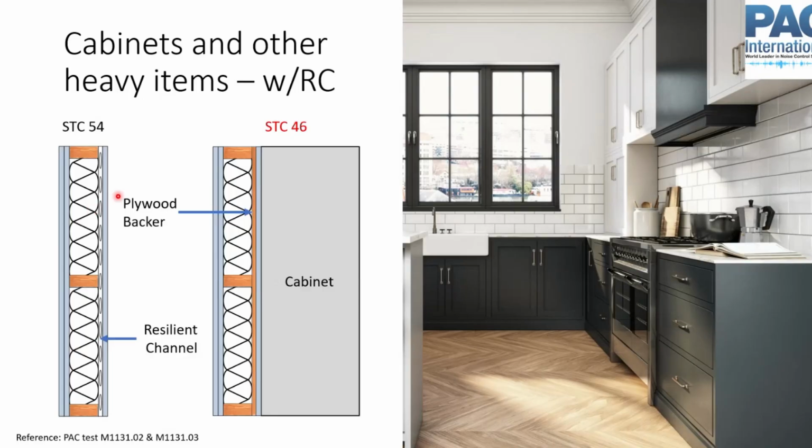So let's take a very basic wall. I was an acoustical consultant. I did a lot of multifamily apartment projects here in the Portland, Oregon area. And most of those, the demising walls, were 2x4 wood studs with resilient channel and some number of layers of drywall on either side. So here we have a tested wall that in this configuration, this test got STC54.